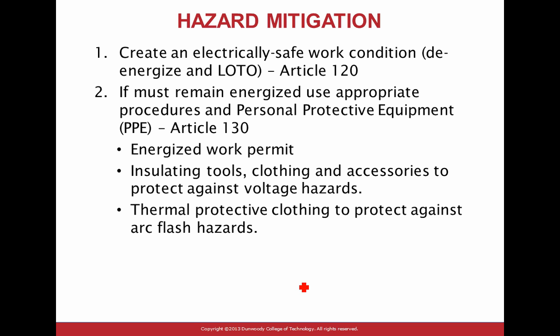I did a short circuit analysis with SKM for us at Dunwoody, and we have a piece of equipment, 3000 amp 480, coming to feed the building. I don't know if you're familiar with the six disconnect rule. It allows you six disconnects without a main. If you see them when you come into a building, there will be 1, 2, 3, 4, 5, 6, with no main. If you work on that piece of equipment, terminating, energized, or torquing, I did the analysis.